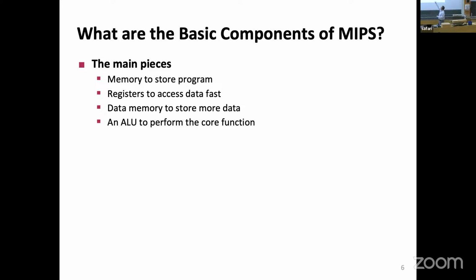What else? Well, we have one memory to store the program. This is here. And then we need one memory to store the data. Technically speaking, you could imagine that these are the same memories. Just for didactic purposes, just imagine that they are two different memories for this part of the lecture. The memory is large. If you remember, the addressable memory is large. So rather than one single memory, there are multiple smaller memories. And usually the data and the program are stored at very different locations. This also means that physically, they would be written in different parts of the memory. And in this case, let's just assume that we have two nicely separated 32-bit memories.